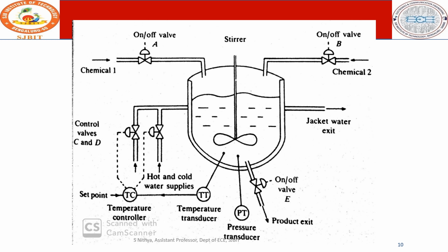And the third step is start stirring to mix. Okay, the stirrer mixes the chemicals, and we repeat the same steps: opening the valve A, and step 2, I mean checking the amount for chemical 2 also, and open the valve B and send the chemical 2 and measure the values. If it reaches the specified amount, then close the valve B and repeat and mix it well. So these are the operations.